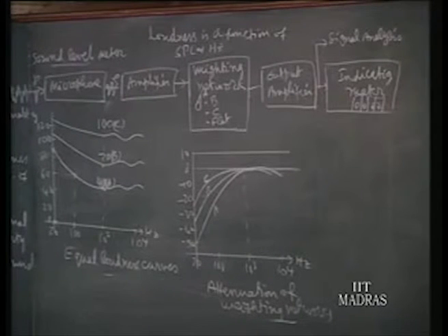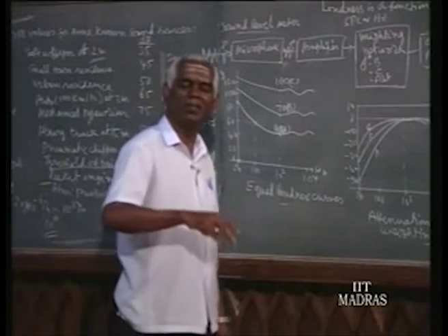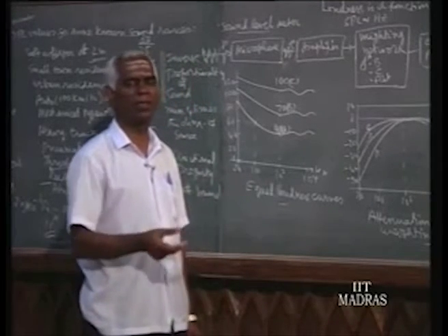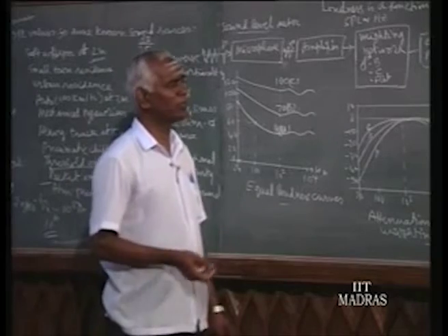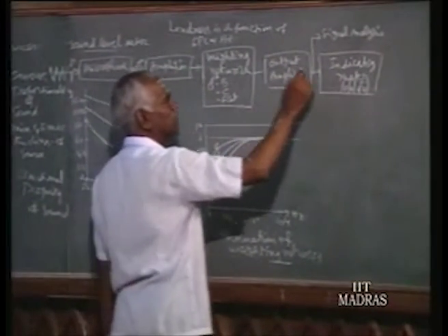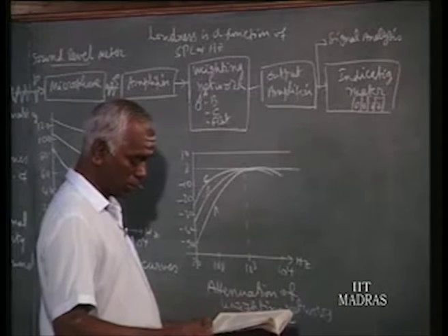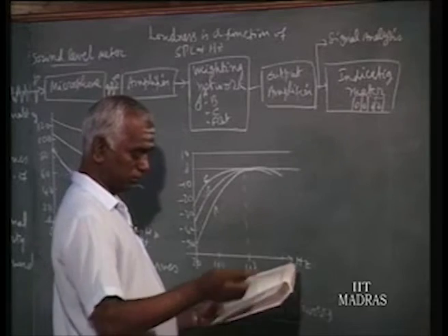An equipment is made up of hundreds of parts, and we would like to locate which part makes the maximum noise. If we locate that part, then probably we will change it to another part making less noise. So for such purposes we have to analyze that signal, for frequency analysis. It is done with the help of an octave band analyzer.